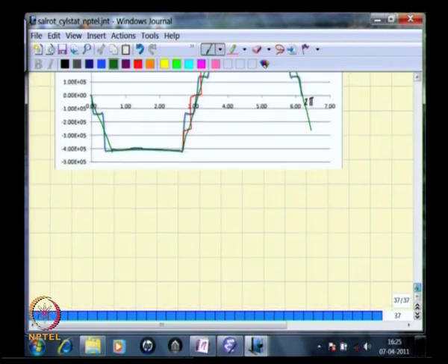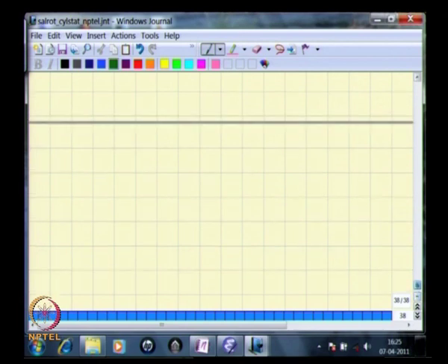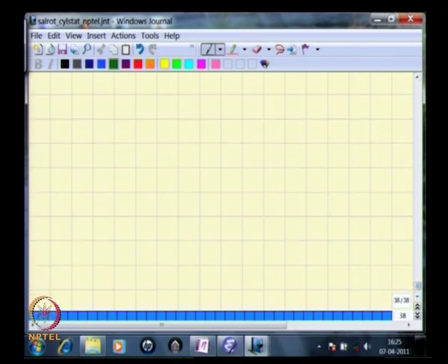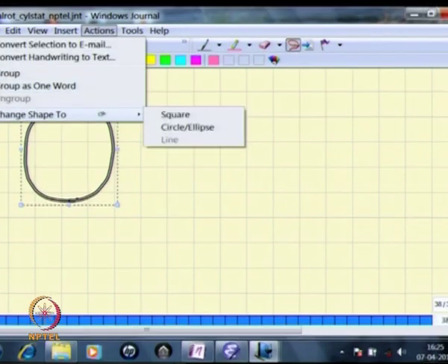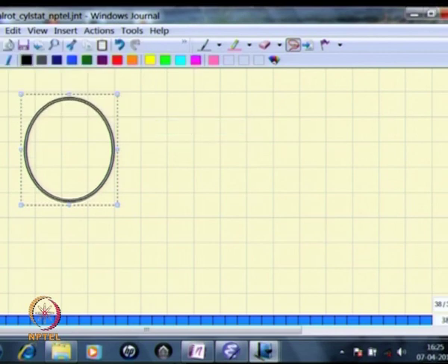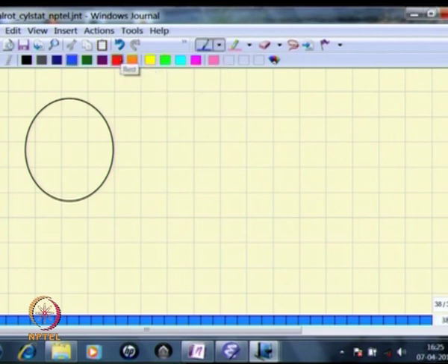So that is the MMF waveform that we have to consider. Indeed, what we can say is that in the limit, let us say we have a circular stator, and we distribute the windings in a uniform manner all over this place, and then the return conductors are distributed in a uniform manner here.